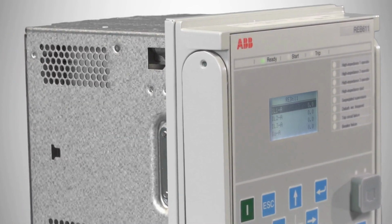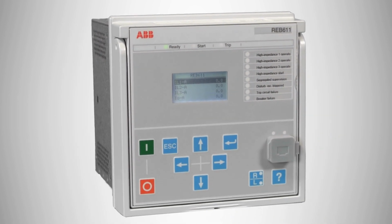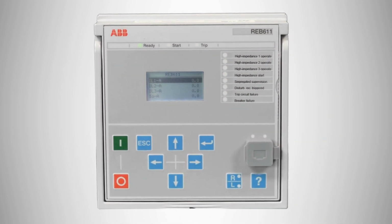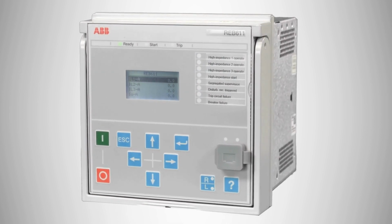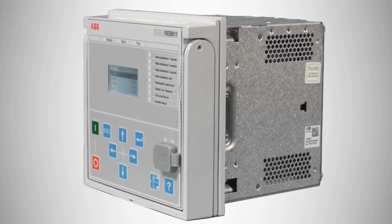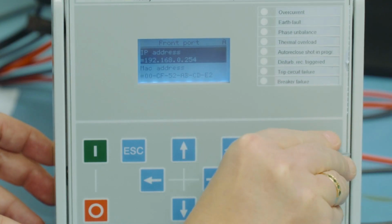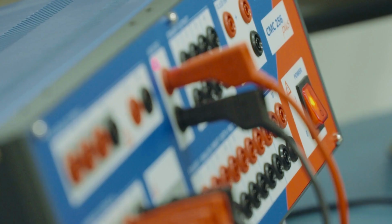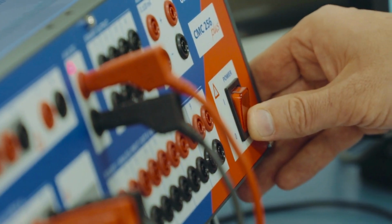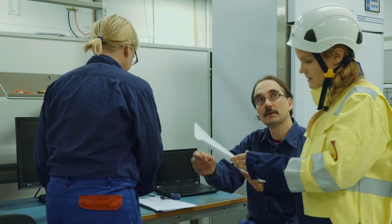The local HMI consists of push buttons, a graphical display, a front communication port, and alarm LED indicators. It is used for parametrization, monitoring, reading measurements, and controlling the primary equipment. The collected data is verified against the results retrieved from the bench test. The fault was found caused by an overload in the feeder.